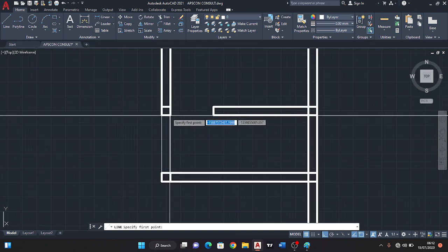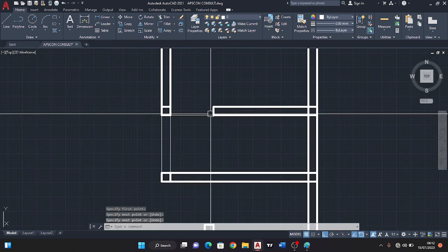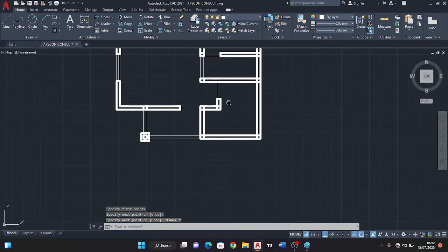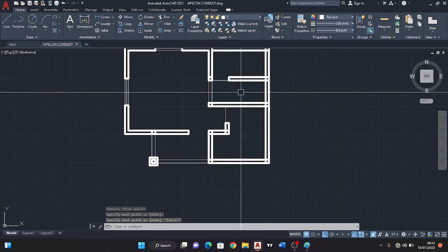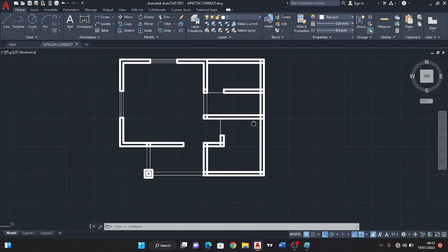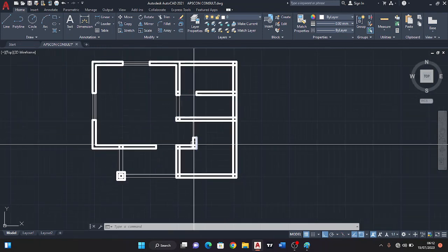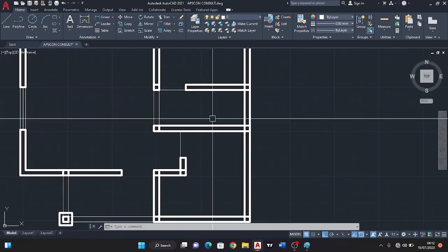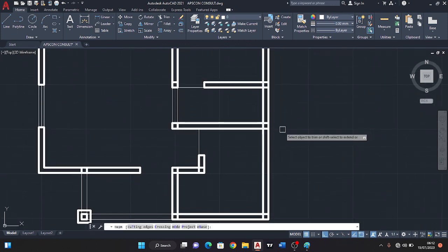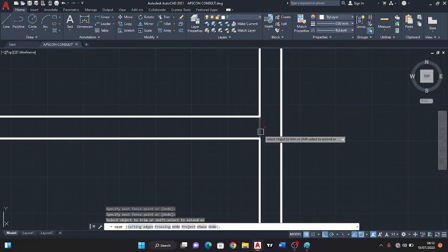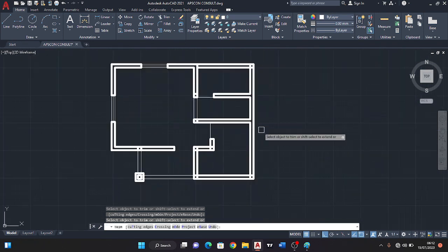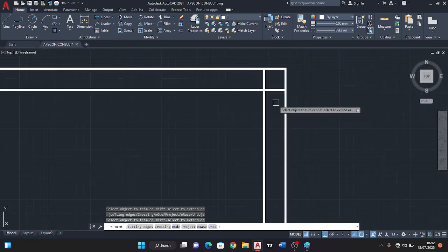So that means there will be a door at this point. There will be another door at this point. You understand? Trying to separate the toilet from the kitchen. They should have no direct connection, so that we'll be able to enhance our neat and sanitary environment in terms of healthy living, and to regulate the air or ventilation.